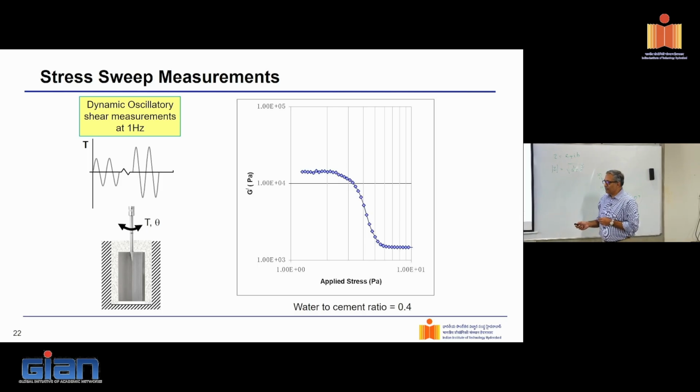And what we measure from there, we can measure both the elastic, which is the solid response, and the viscoelastic part, which is the G double prime. If you look at the elastic response, it would initially give you a constant G prime. What does that mean? It gives you a constant shear modulus. So what am I measuring here when I do a small agitation? I'm going back and forth with a small amplitude.